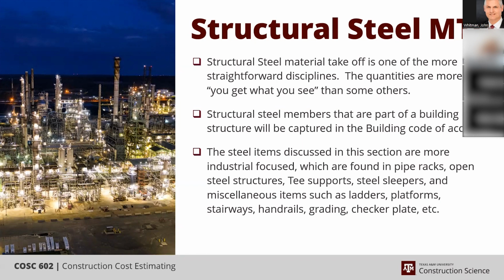But the skin is really just acting more as a windbreak, or maybe trying to keep rain out of a certain process area. So you could have a portion of the building, like one side of the building may have skin, or 2 sides and the other 2 don't. So that's something that happens on occasion. But the main task of that structure is elevating the equipment and supporting the equipment at height.